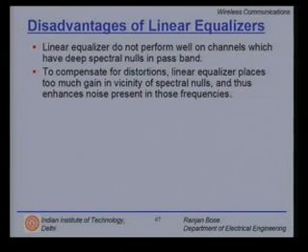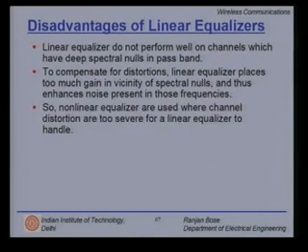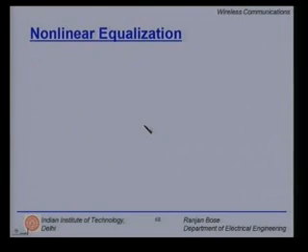To compensate for distortions, linear equalizers place too much gain in the vicinity of these spectral nulls and thus enhance the noise present in these frequencies, not good. So, nonlinear equalizers are used when channel distortions are too severe for linear equalizers to handle. That is where they step in. So, let us now move into the domain of nonlinear equalizers.